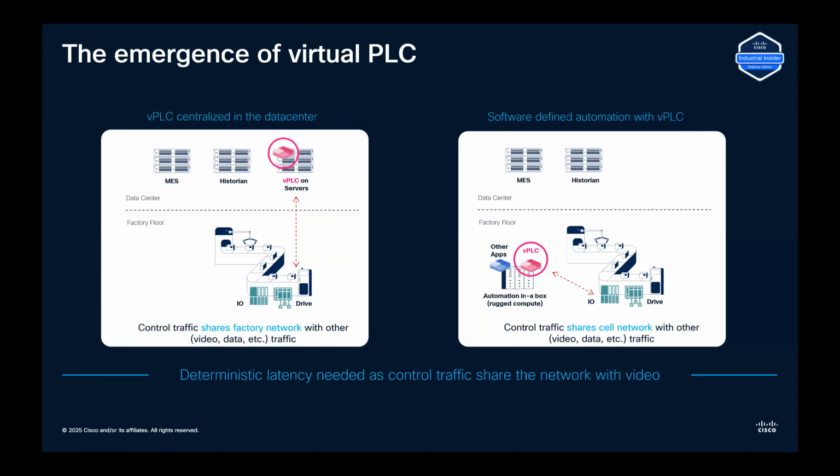And this timing has to function over all the other things going on in the same network. The same network might be handling your vision systems, with big data pipes going, and it now has to handle these control messages too, and you don't want your heavy duty video frames interfering with this control traffic.